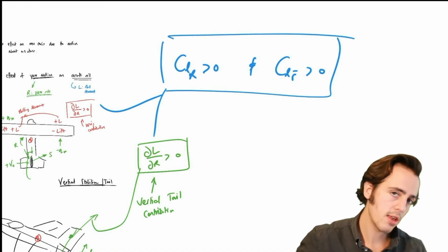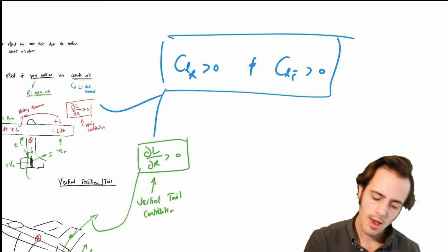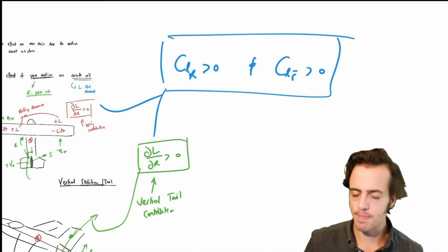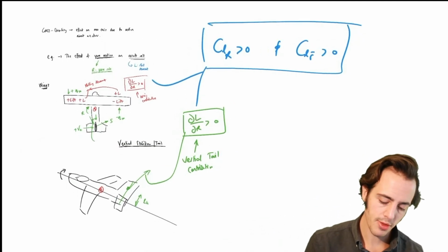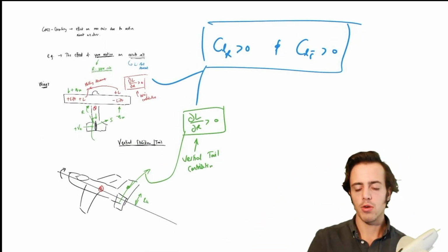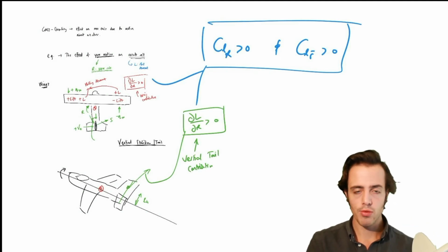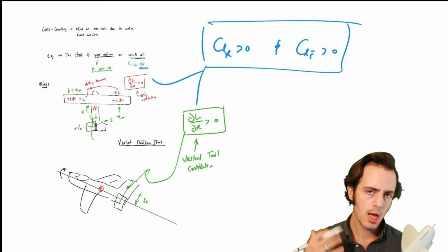Okay, we would change the actual magnitude of these derivatives if we were looking at the numerical value, but the sign of them we'd expect to be the same. And we can think about the different parts that are going to affect them. If you're on, say, the Tornado, a very large tail is going to increase the tail contribution to CLR.